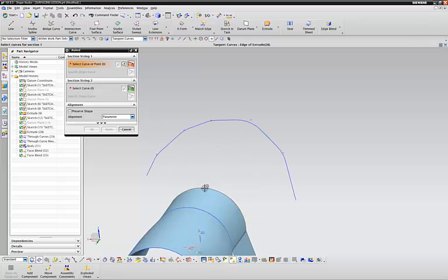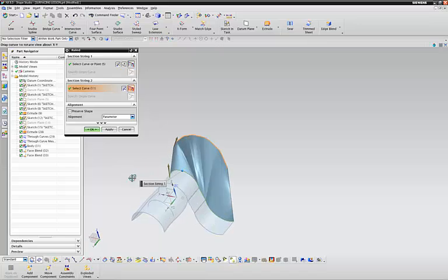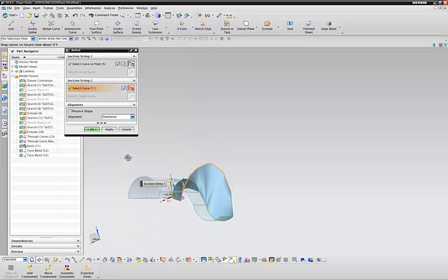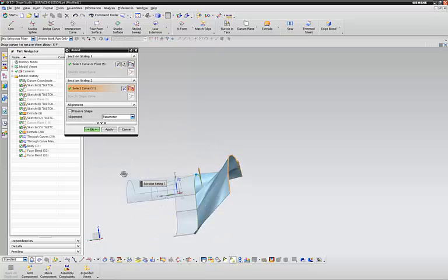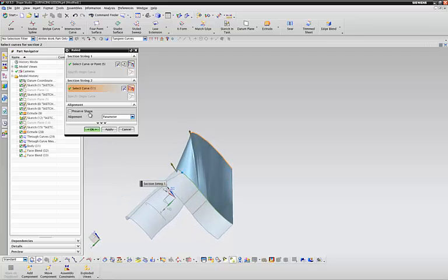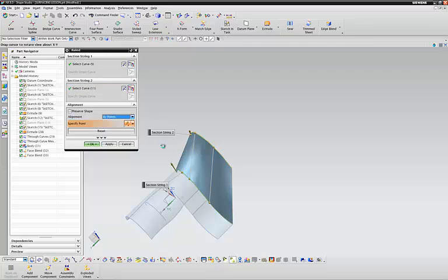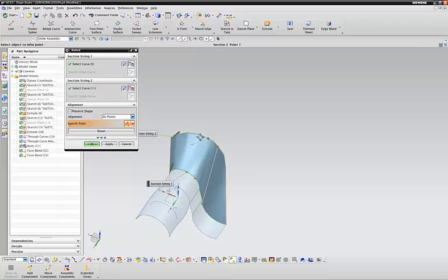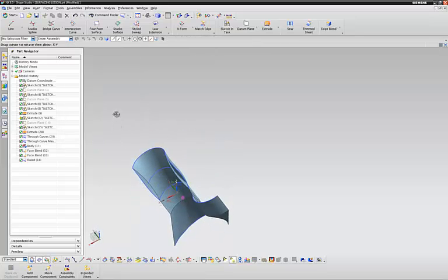We'll click on our first surface, click on our second one, and you can see it attached through everything, which is alright if you want it that way. You can change the parameters here by points. You can change these points around on how it connects the locations between these objects depending on your needs.